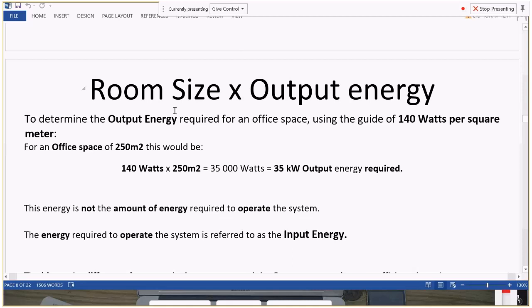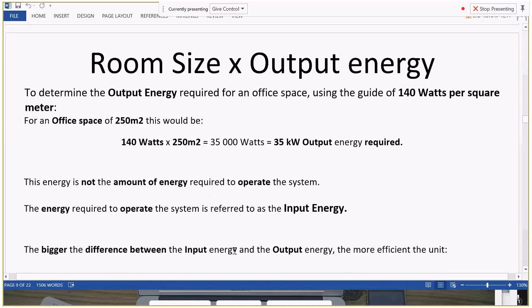So for our energy calculation, we're going to be doing that at 140 watts per square metre. That's how many watts are required. But given that all of that is embedded in that calculation sheet for you, what you have to do is determine the air conditioned space, so the office space and the corridor, and then put that into the spreadsheet, and it will say, okay, efficient system requires this much electricity, inefficient system requires this much electricity.